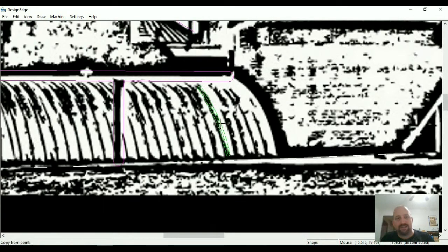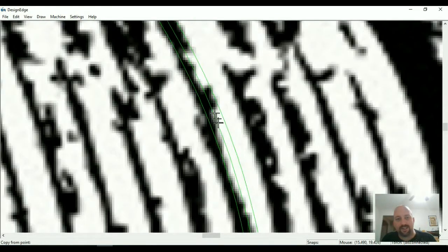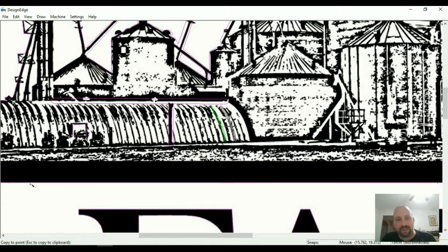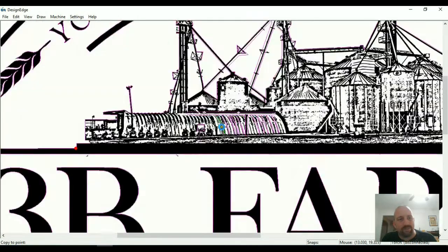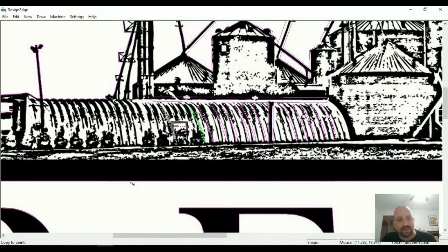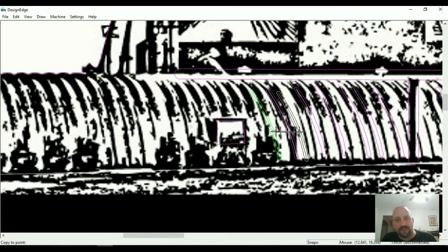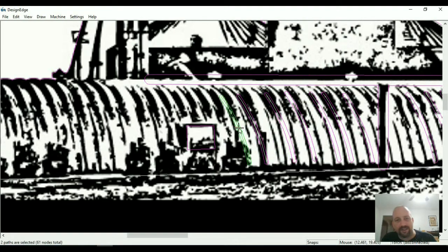Now that line can stay in there, and then I'll show you what I'm going to do. So I'm going to C copy, and I've got both my center line and this outside view piece selected, and I'm just going to copy that kind of at random down through here. I don't want it to be too exact. That's really not what I'm going for. I may have to rotate that just a little bit. As it comes down here, the angle we're viewing it changes. So I'm going to rotate it a little bit.